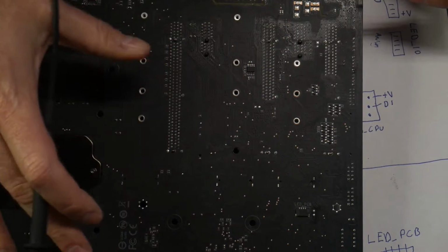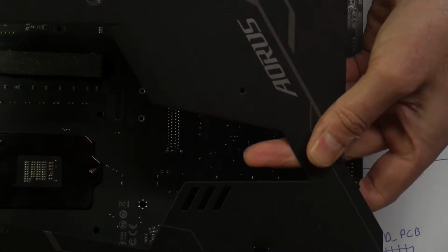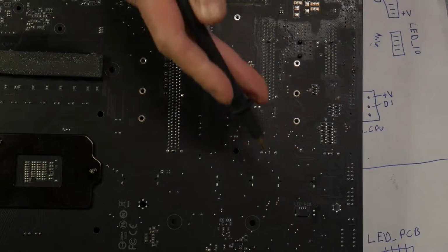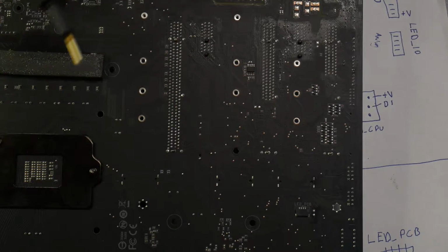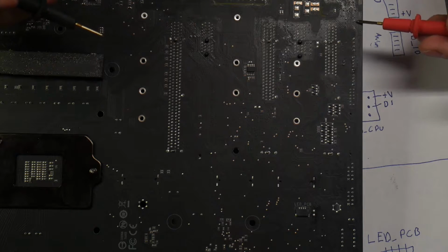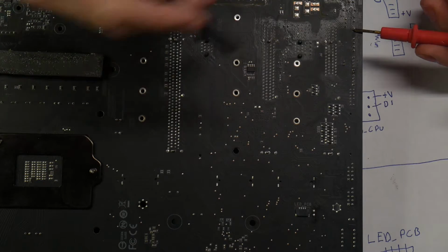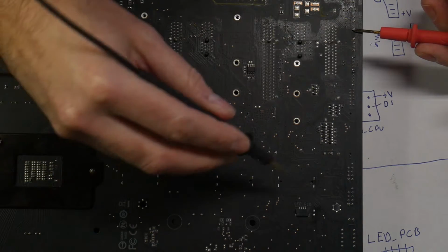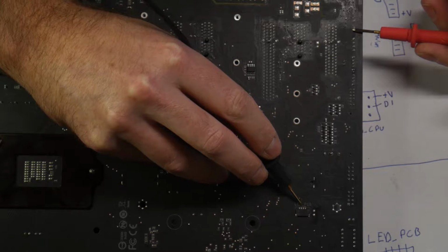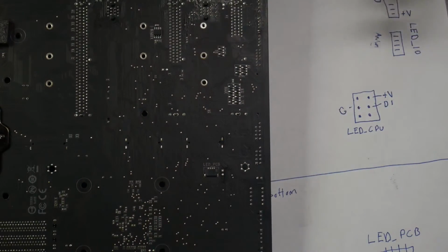And most motherboards I see don't have lighting on the back. This motherboard has a little RGB LED strip in the front that connects to the bottom header, and we're going to map that one up and figure out what it is. So right here I noticed these pins, and I know this is the weird form factor that addressable LEDs have from the backside, and you can also flip it over and compare it. So I know this is going to be ground, and so I'm going to look for ground over here. Yep, first try. And that's voltage. So ground is this side and voltage is this side. So what I'm going to do is mark that.